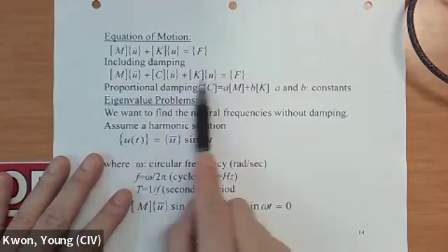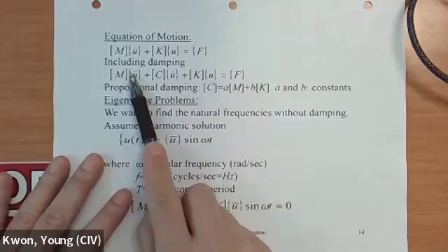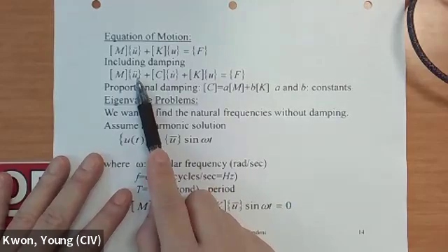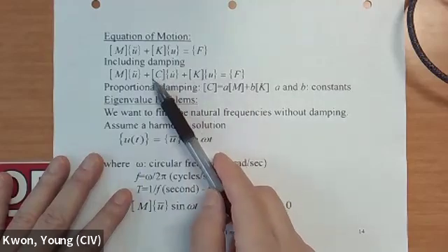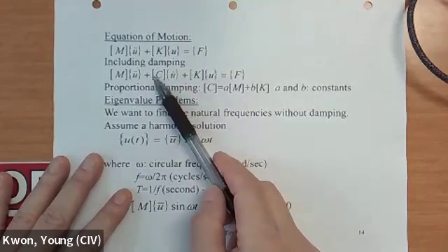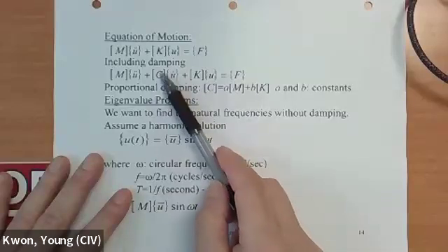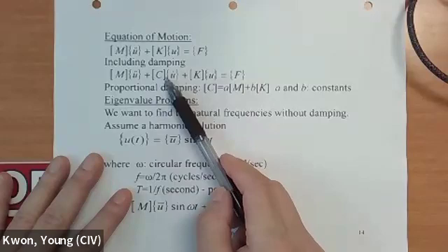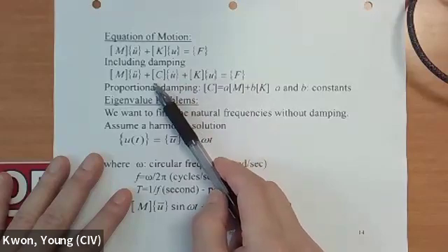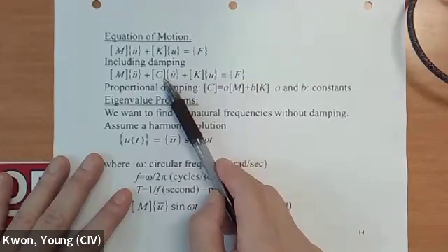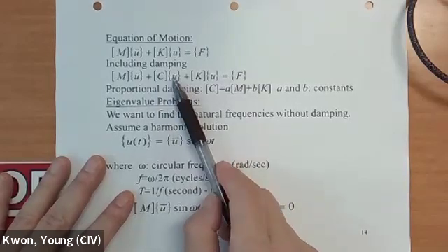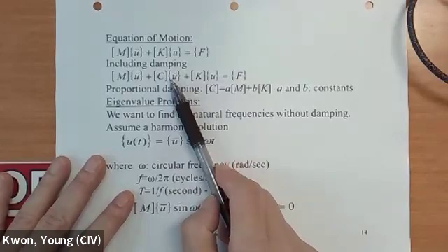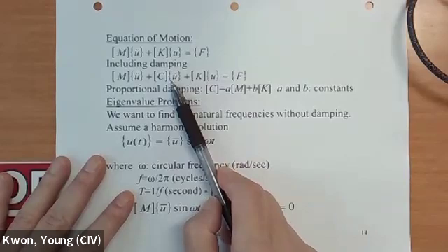This is going to be the equation of motion in whatever degree of freedom, the size of the matrix, I mean this column vector. And the damping term, you may already know, is usually not coming from mathematics, because in virtually no cases, except very simplified cases, can we derive the damping term from a mathematical equation. So that is more or less an empirical expression, from experiment or some observation, and then they just come up with some kind of damping term.